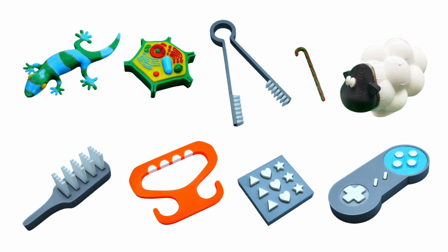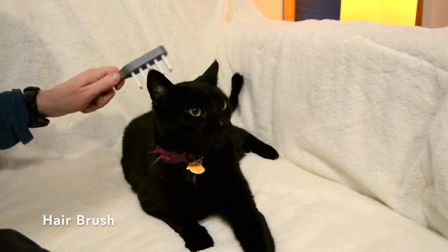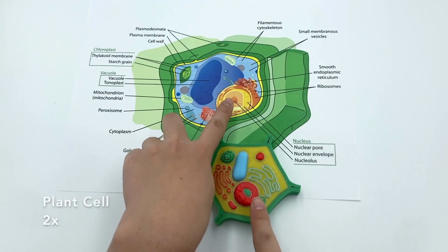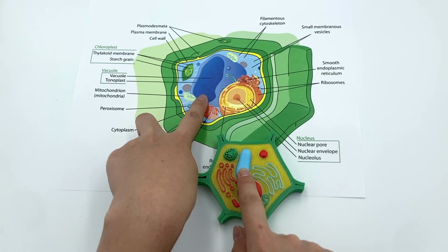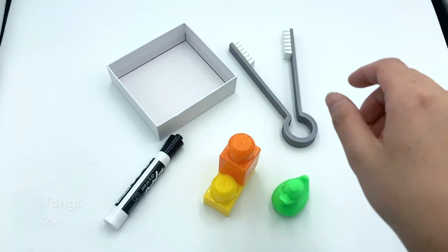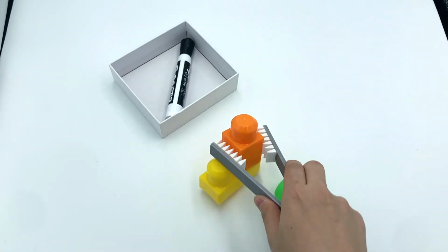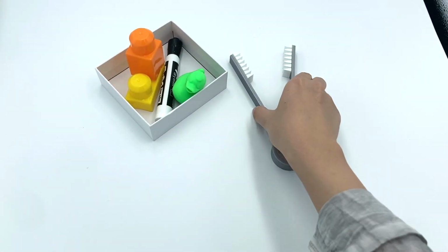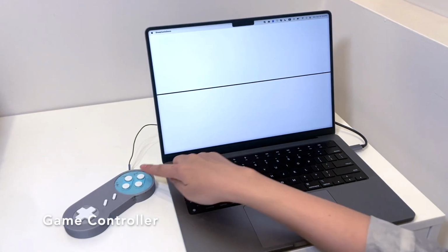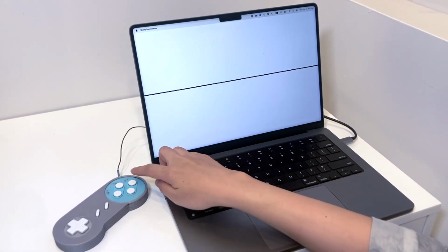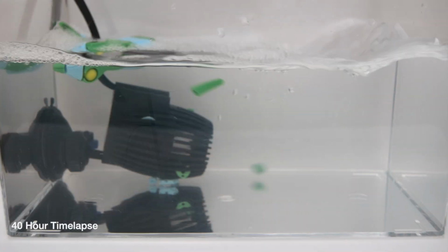To demonstrate our computational technique, we processed and fabricated 9 objects that have different structural, functional, and aesthetic qualities. Their interfaces are printed with water-soluble PVA. At their end of life, these multi-material objects are submerged in water, and their interfaces dissolve to enable disassembly.